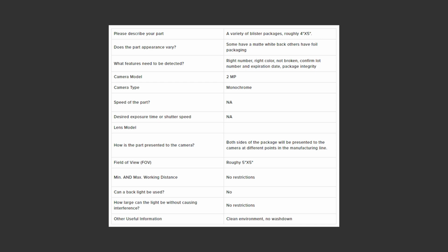And last, another factor that gets overlooked is fixturing. Often, when we're doing testing on a sample and when you're testing in your own lab, your part is sitting just on a table and there's nothing to interfere with how the light reflects off of the sample. But every once in a while, we get a fixture where when the part is in the fixture on the machine, that is blocking the light at the angle we want it to hit the sample, and it no longer solves the application. So it's something that gets overlooked a lot.